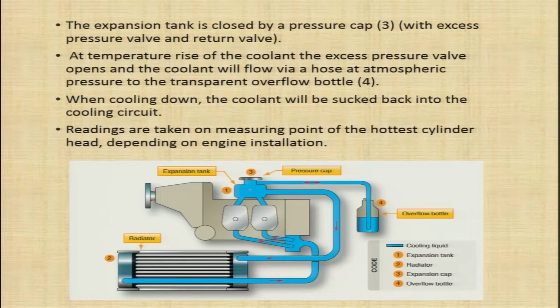Because of the increased temperature of the coolant, the excess pressure valve in the pressure cap opens, and the coolant will flow via a hose at atmospheric pressure to the transparent overflow bottle.